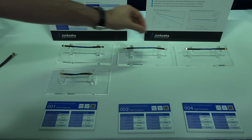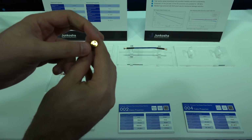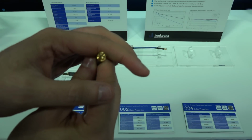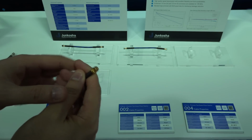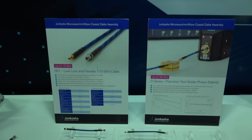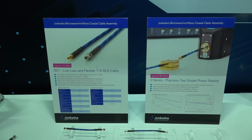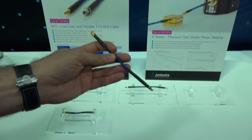At the same time, this is a more rigid version of that cable, but they can make this also flexible. This is now a 0.8 millimeter connector, which is very hard to see on camera, but this would go all the way to 145 gigahertz. And in particular, with any heads that do support that frequency range, you can do a single sweep up to 145 gigahertz. Yeah, huge advantage being able to manufacture every aspect of the cable yourself,